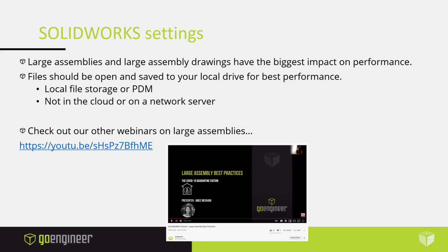One thing that I have to mention as far as performance goes: some of the performance issues, like slow opening and slow saving, have to do with file storage. So is more better? Well, in this case, if you're working in the cloud or on a server, we see some instabilities and some issues from time to time, and then the answer would be no, we just need to try a different file storage method. Move your files locally, or use PDM. PDM automatically moves those files local for you, but that could have a huge benefit as far as performance goes.